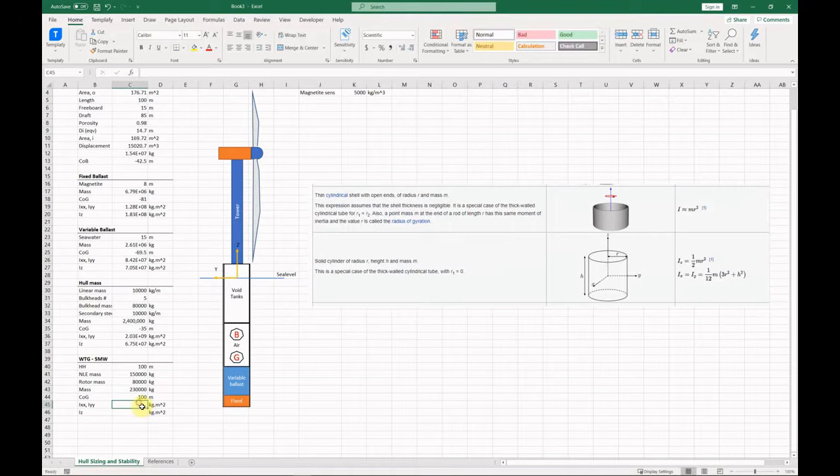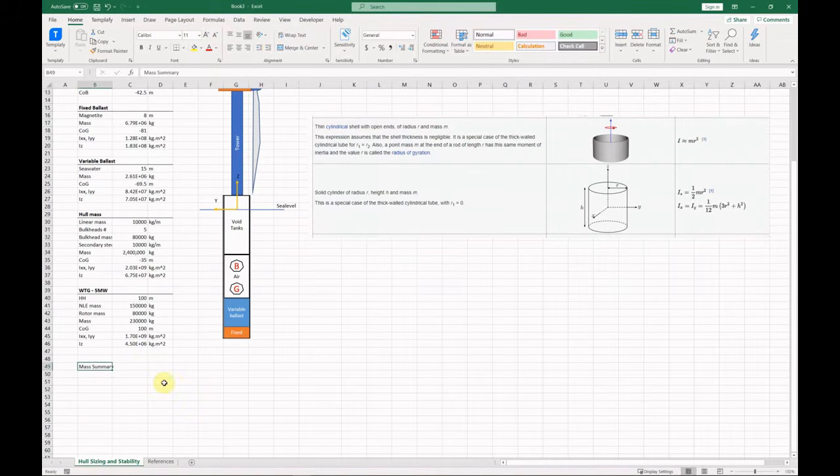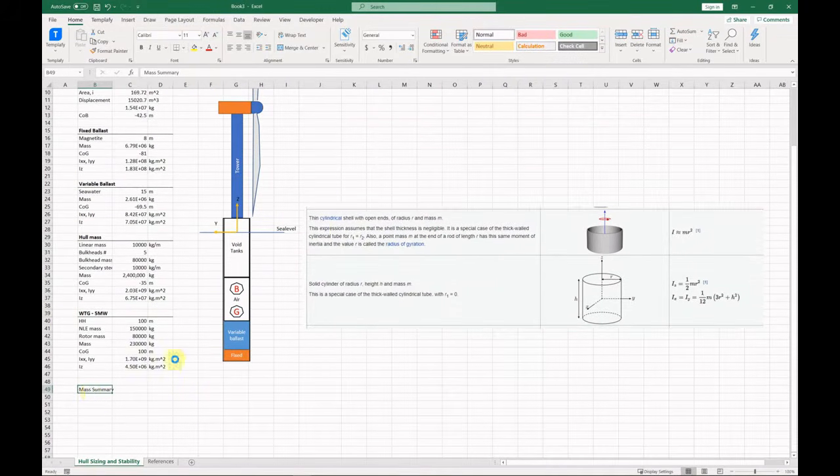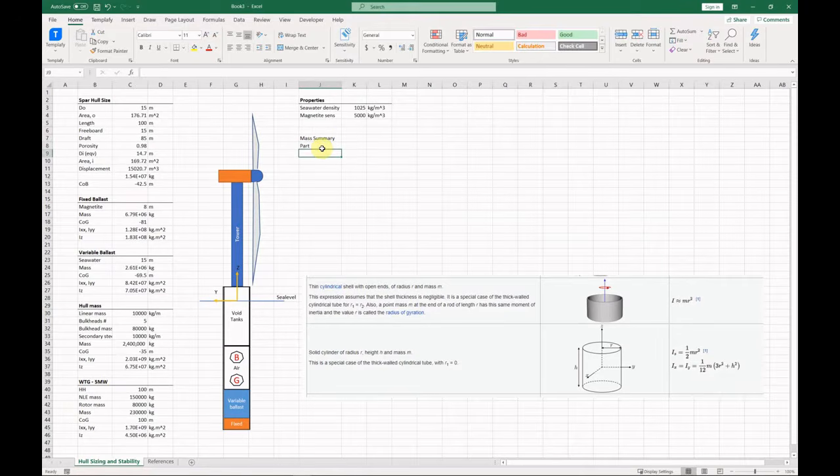The inertia of the nacelle can be simplified as a brick with 2 meters wide, 3 meters high and around 5 or 6 meters long, with distributed mass. Let's ignore the hub inertia and the blades as well. They are very flexible and may not contribute much. To consider blades would also be much more complicated, as their properties depend on pitch angle.